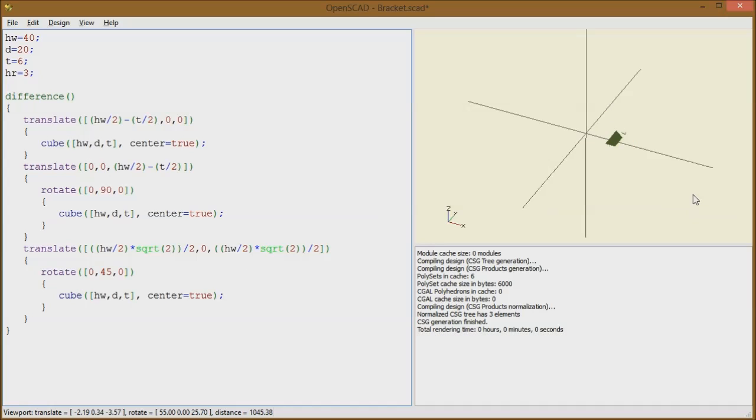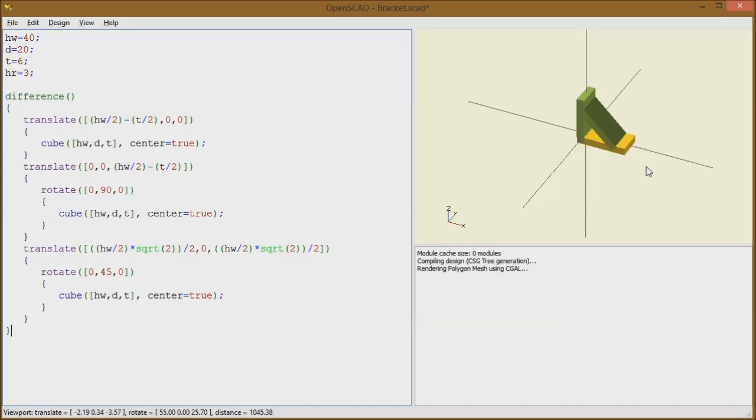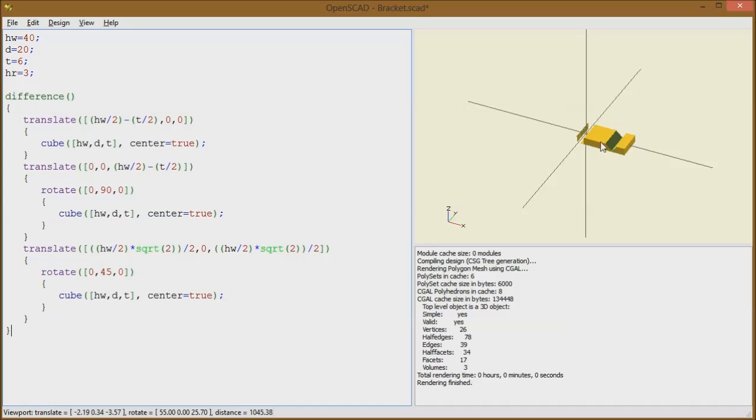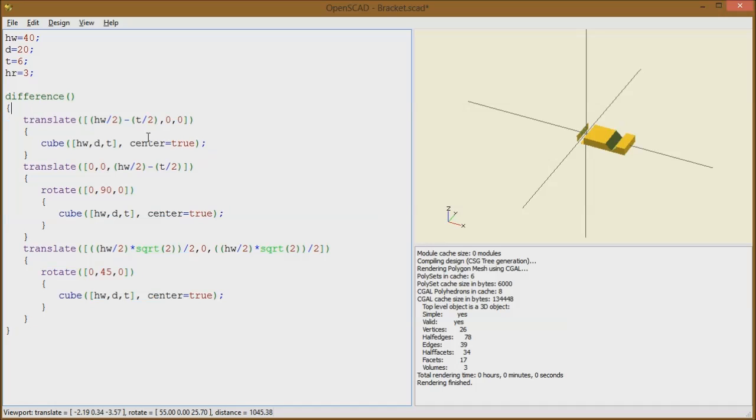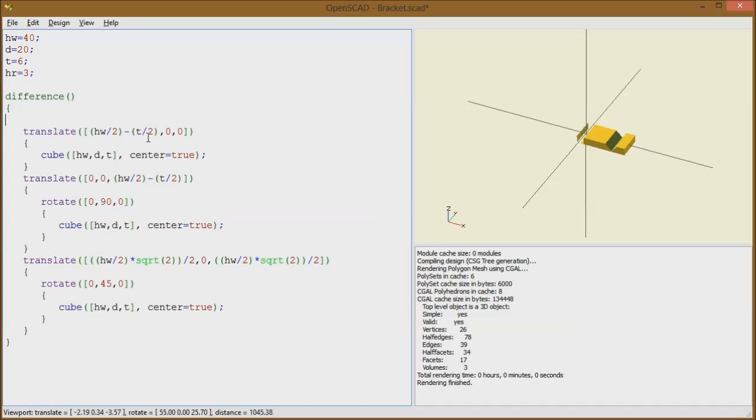So it'll place that one and cut these shapes out. So if I press F5, well, you really can't see anything. If I press F12, you'll see that only the first cube is there, and the rest is cutouts from that cube. So if I do a full render and press F6, that's the object you're going to get hold of, right? So to combine all of these shapes that we have done so far into a single shape, you'll want to use a union method.